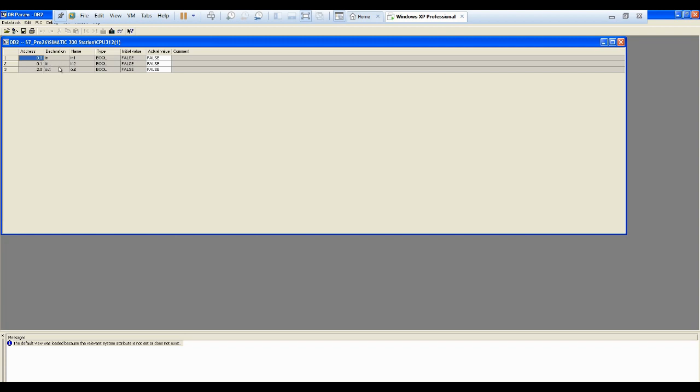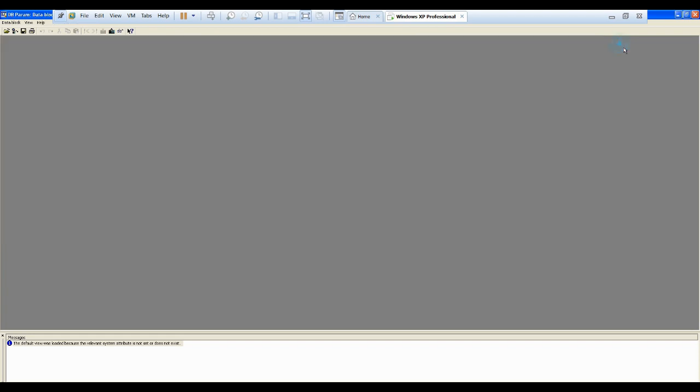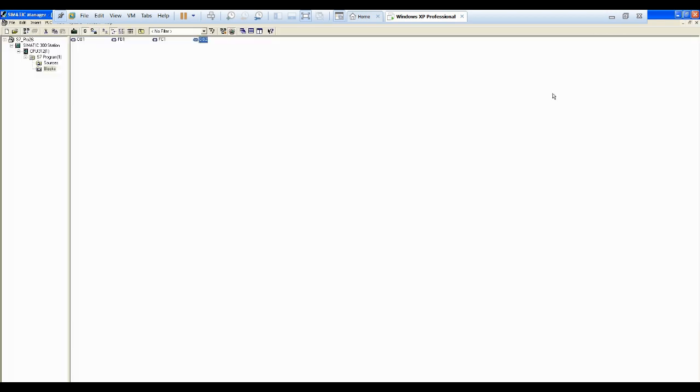So you can see here we have in1, in2, and out. So we have two inputs and one output here. Okay, so that's pretty much clear. So we have a data block that contains all inputs and outputs in FB, and that was not the case in FC. You remember that.